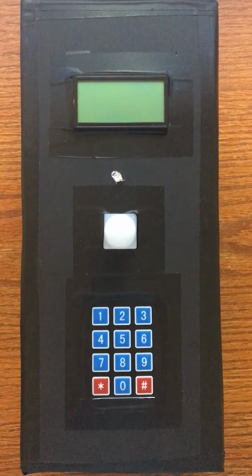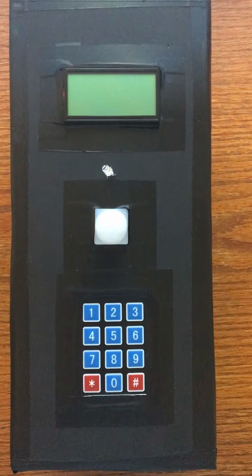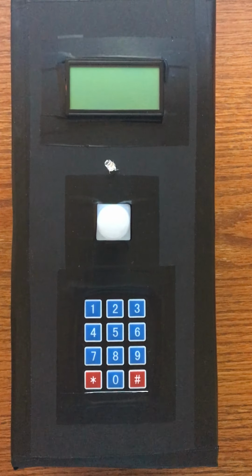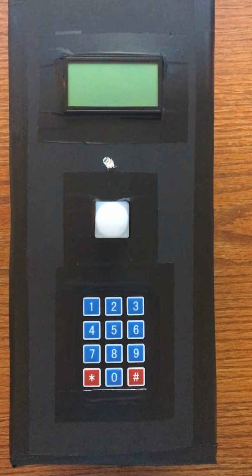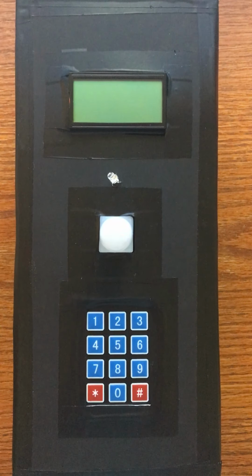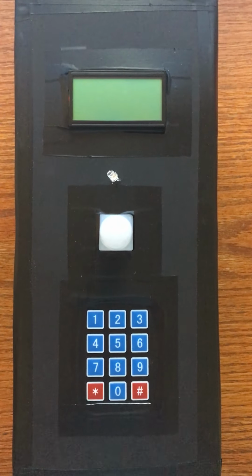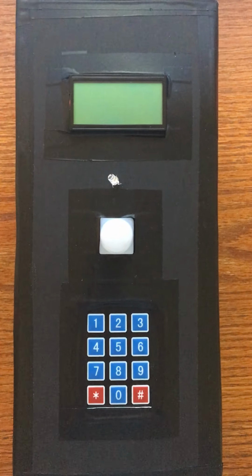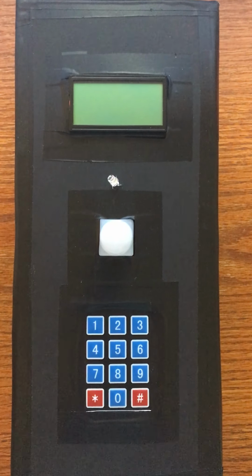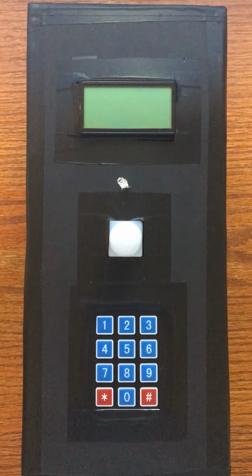It consists of the MSP432 microcontroller integrated with a battery pack, a passive infrared sensor, an LCD module, a keypad, a digital to analog converter, and a red LED. When the alarm system is engaged, the PIR sensor acts as a motion detector. If the sensor detects motion, the alarm is tripped and the LED turns on. To deactivate the alarm, the user must input the correct 4-digit PIN using the keypad. To reset the alarm, the user must press the star key.